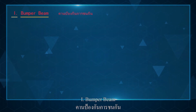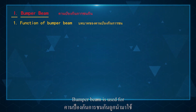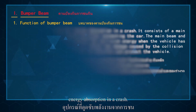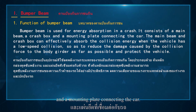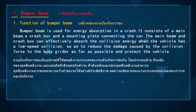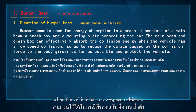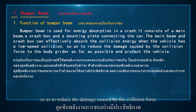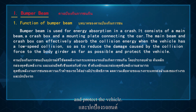1. Bumper beam. Function of bumper beam. Bumper beam is used for energy absorption in a crash. It consists of a main beam, a crash box, and a mounting plate connecting the car. The main beam and crash box can effectively absorb the collision energy when the vehicle has a low-speed collision, so as to reduce the damage caused by the collision force to the body girder as far as possible, and protect the vehicle.